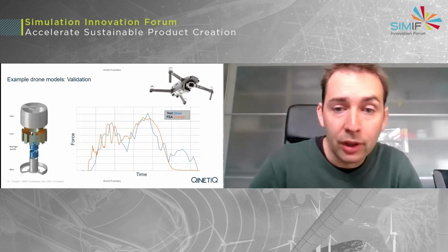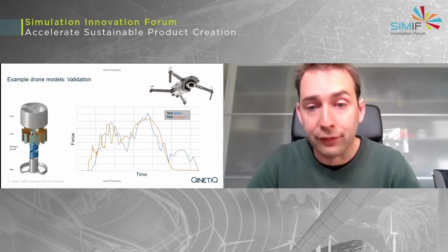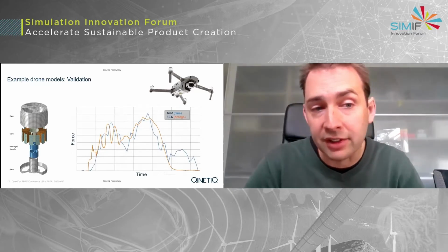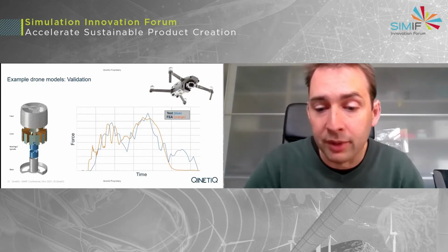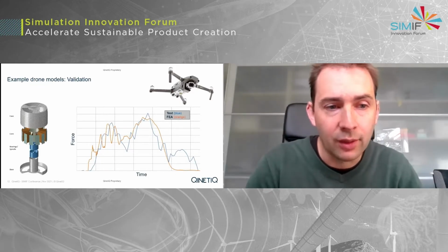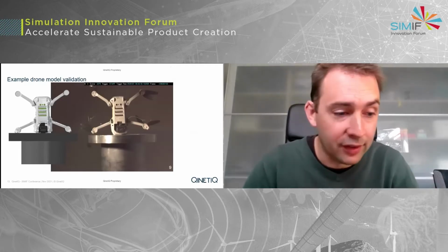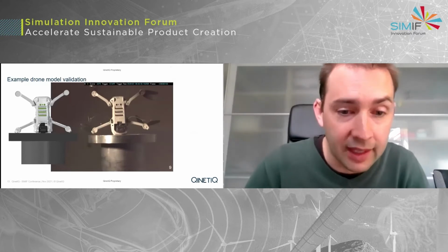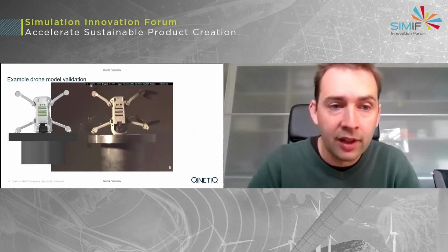What we see here in the blue is the results from the test, the force time response from the test, overlaid with the analysis predictions for that same scenario, which is obviously modelled alongside the test conditions. So of course, this is repeated a number of times for the different drone components, the motors, the batteries, the camera systems for each of the drones.